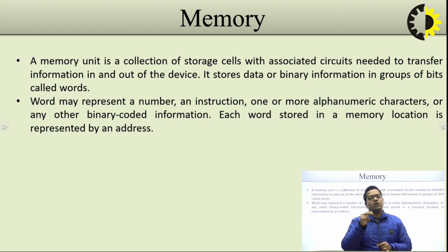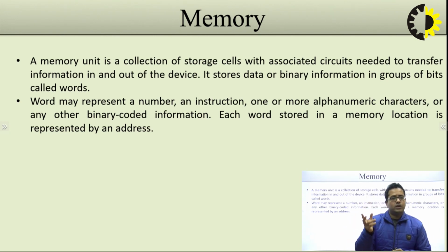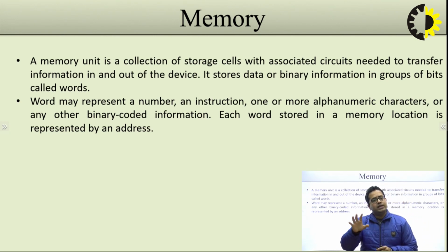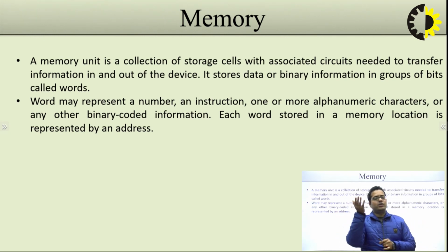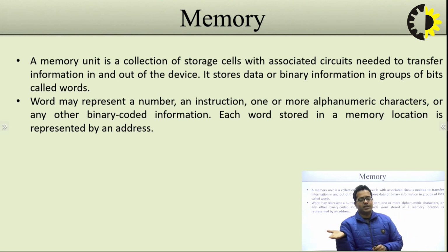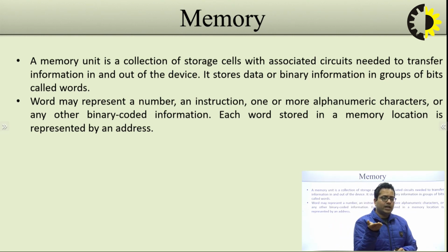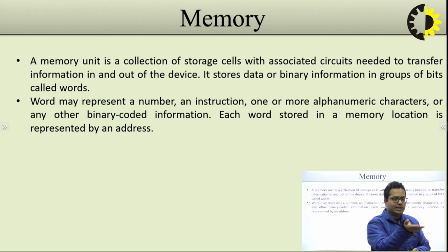That something is called a control. A processor is controlling whether it wants to write or read the contents of that particular memory location. That is done by a control bus. So once, out of the million locations, a particular location is selected, your memory is waiting to know whether it has to read it or send that data.